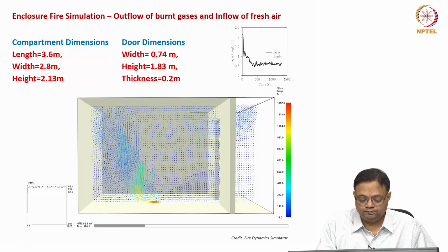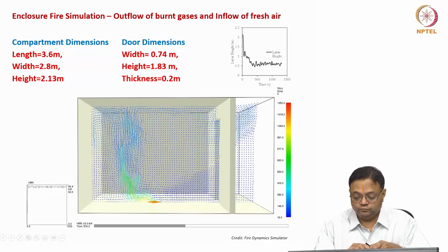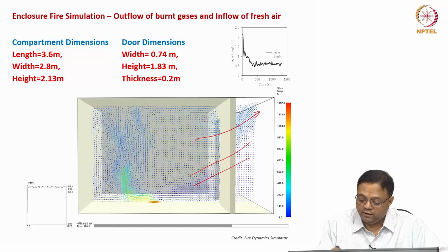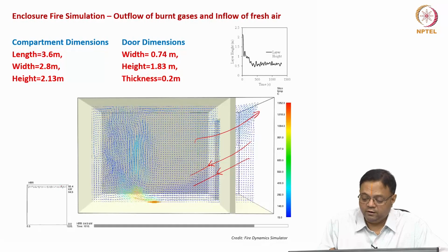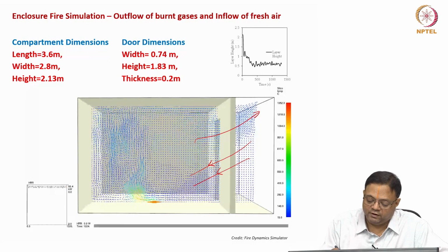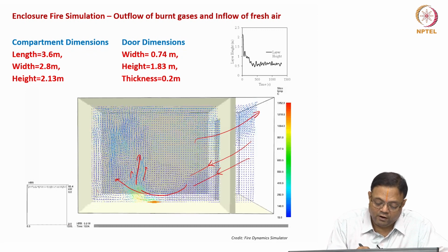as the fire burns, air comes in from the bottom portion here. Air comes in the bottom portion, and gases are escaping, air is coming down like this, and actually entrainment is very severe because of this big door opening. So entrainment is very severe, it actually pushes the fire towards the left side of the wall, and you can see the dynamics of the flow. In general, we see the hot gases rising up, and this pushing, creating some recirculation zones, and a lot of turbulent activity.